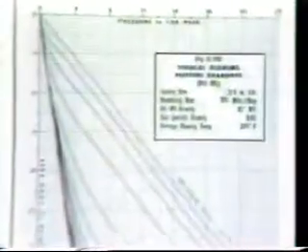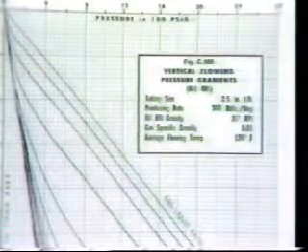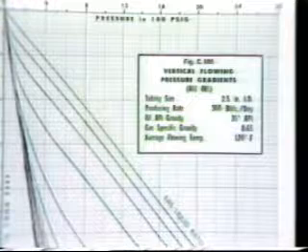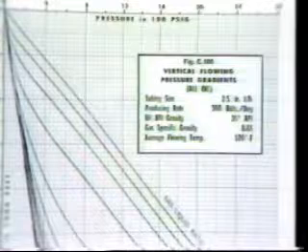This can result in a number of different flow regimes being present during natural flow in a vertical tubing. Because of the complexity of the vertical flow regimes, correlations have been developed which allow us to predict vertical pressure losses in the tubing for a wide variety of vertical flow conditions. These correlations are published as sets of curves, one of which we see here. For any given flow rate, tubing configuration, and production fluid characteristics, the pressure drop in the tubing from the bottom of the hole to the surface may be estimated using these correlations.